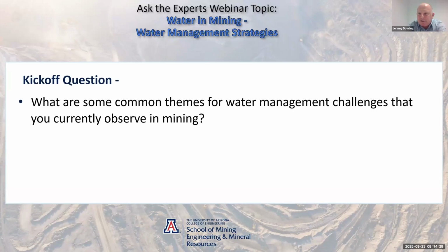And it's become recognized really that surface water runoff feeding in from the drainages and the crest areas and the facilities around the pits, and that water feeding into the shallow parts of the pit slope, into shallow dipping structures and into weaker rock mass in the excavation damage zone, is often the main contributing factor to slope instability in terms of the water contribution.